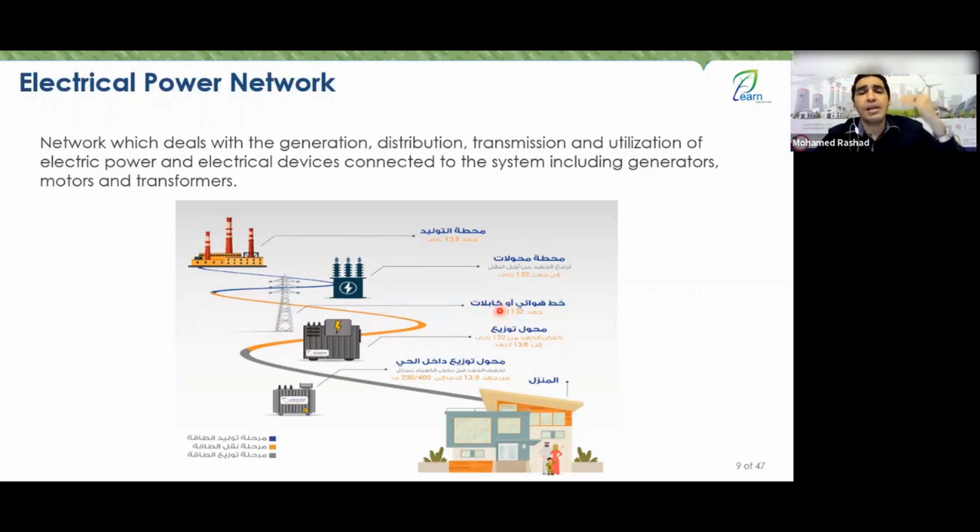to this transformer here, and this is where the electrical current is distributed to various areas. This is the distribution transformer that steps down the voltage again from high or extra high voltage to medium voltage. From medium voltage, it starts distributing, including in your neighborhood where there is a distribution transformer within the neighborhood with a ring main unit. Through this, the voltage is reduced to 400 to 230, and it begins to distribute to your loads. As you can see here, this line up to this point is the power generation stage.